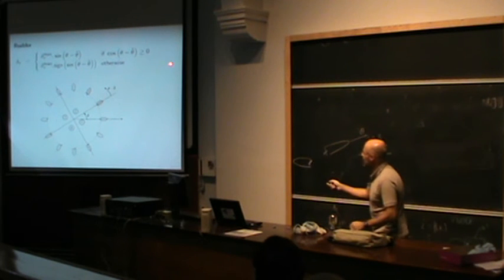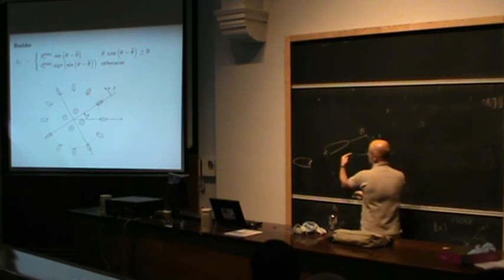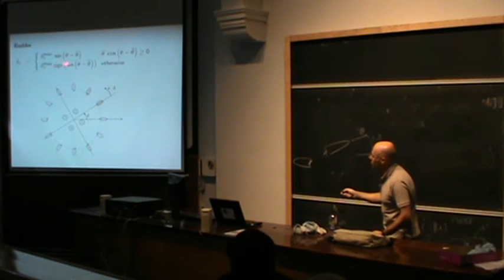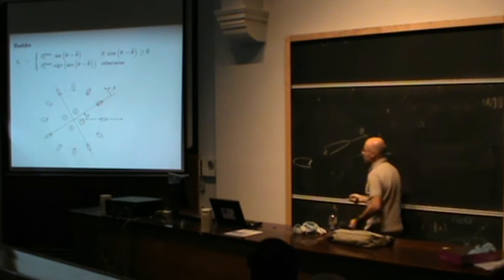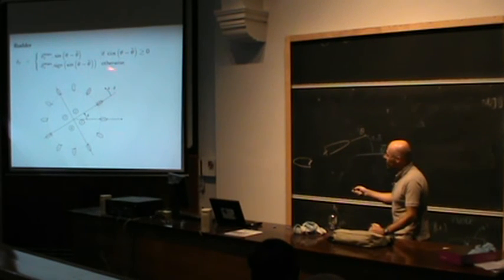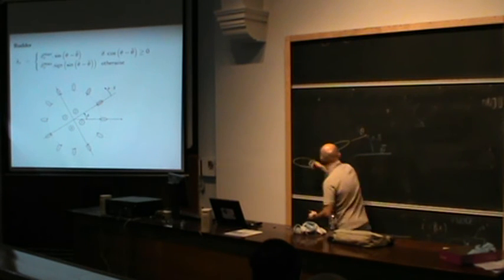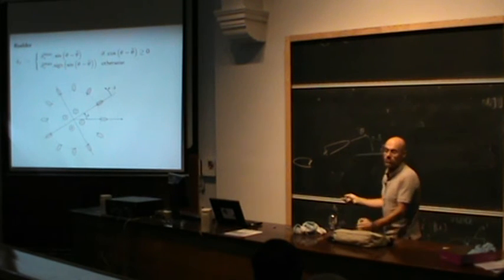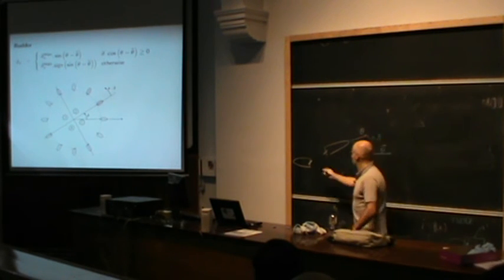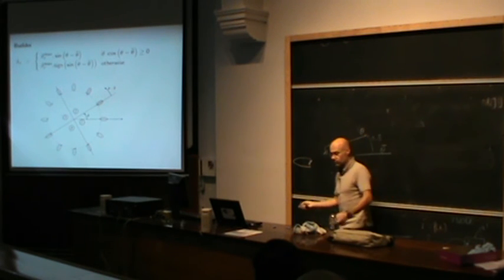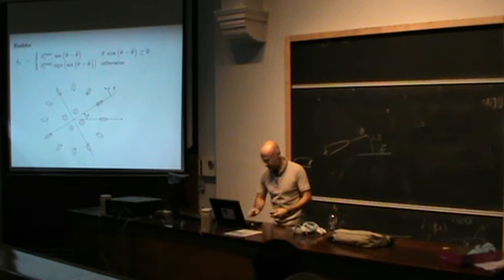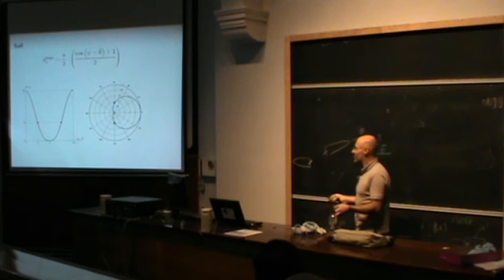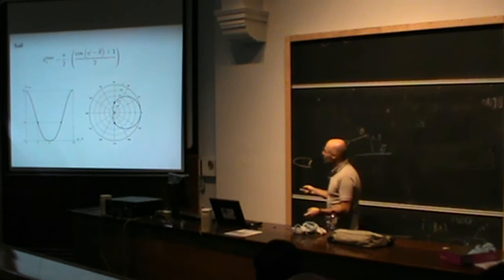That's why when I am approximately in the right direction, I will perform what we call a proportional control, proportional to the error. But when we are in the wrong direction, as here, I want to go there, we'll perform a bang-bang control. So, bang-bang, full on the right, full on the left. Okay? Classical in robotics.